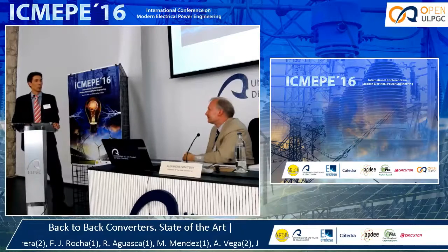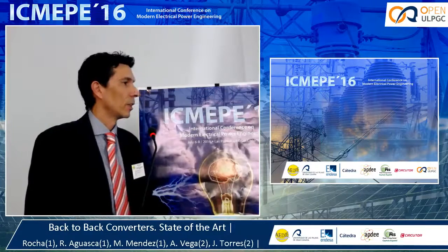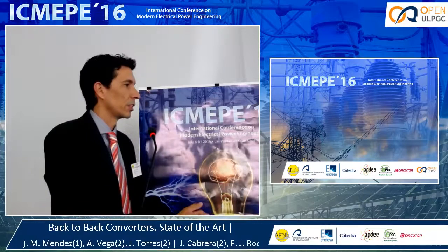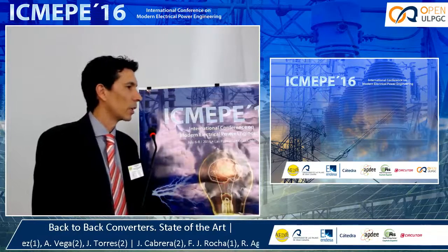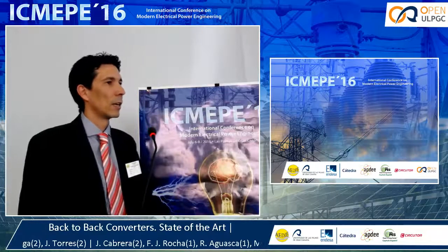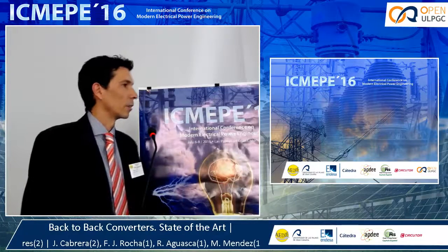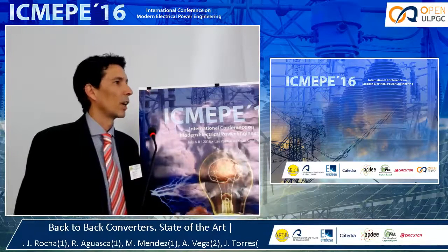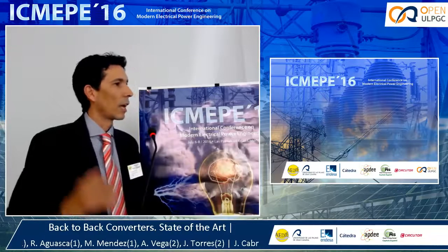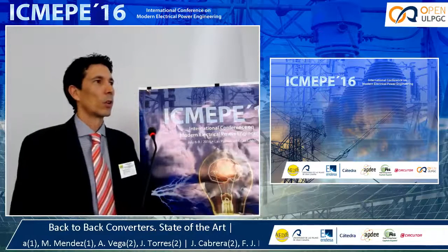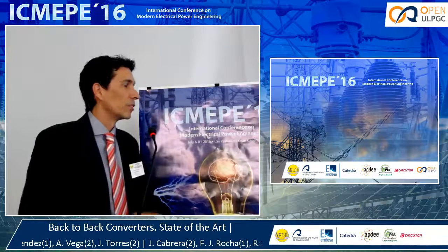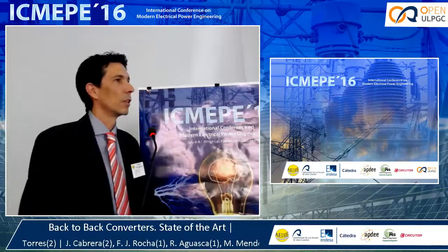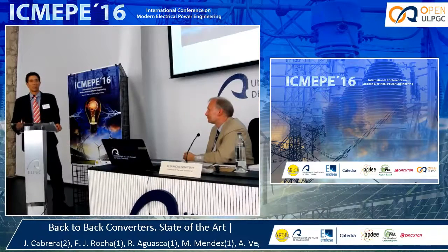to distribute all the generation close to every distributed generation will be power electronics, and it will be at a distribution network level, not a transmission level. Sure. So the powers we are talking about are not big powers, high bulk power. We're talking about distribution, and perhaps the problem is not with the stability. The problem will come with harmonics.